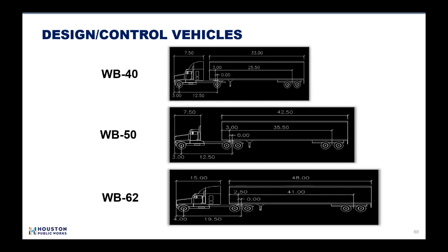We're also phasing out the WB50, which was our standard large truck designation template. It hasn't been supported by AASHTO for a number of years now. I think as early as the middle 80s, the truck mix on the roadways was not really matching the WB50. And so it took AASHTO quite a while to take that out. They're not ones to go and rapidly change things, to their credit. But the WB50, which is in the middle there, is no longer a supported design vehicle.